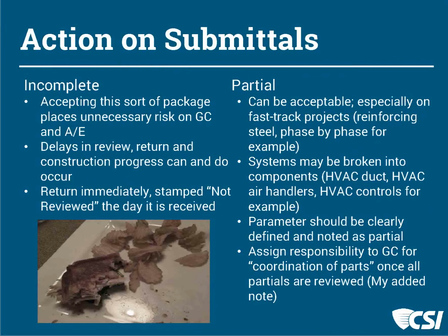Well, I would retain that authority as the designer of record, and I would make that judgment based on what the specifications require. So within my general conditions, I would generally describe what type of submittals, what type of packages are due, but then each component of the specifications in each product also lists what is required for that particular product.